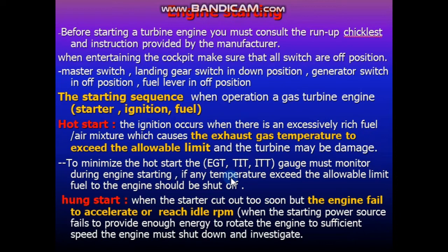Hang start is when the starter cuts out too soon, but the engine fails to accelerate or reach idle RPM, or when the starting power source fails to provide enough energy to rotate the engine to sufficient speed. The engine must be shut down and investigated. That means a hang start occurs when the engine starts and then stalls. So you have to shut down the engine and investigate the reasons for the hang start.